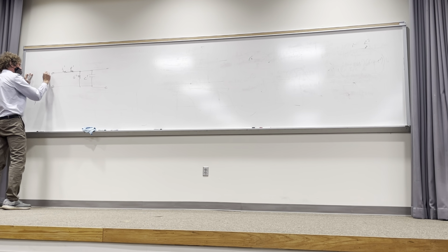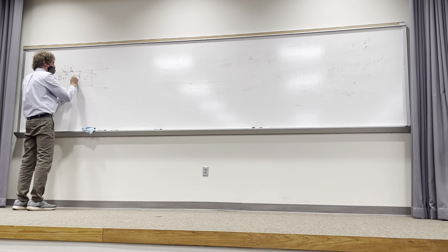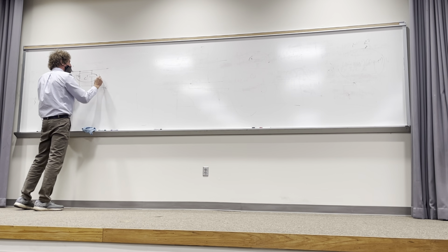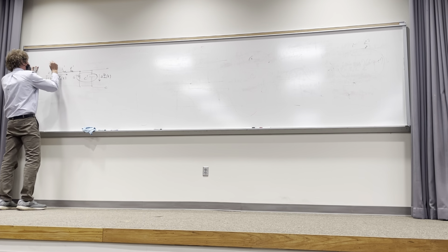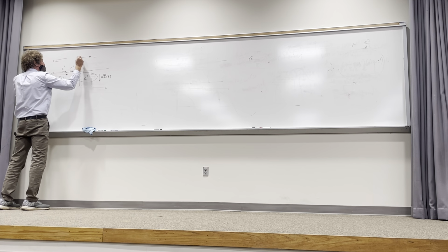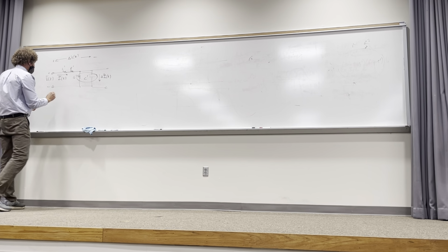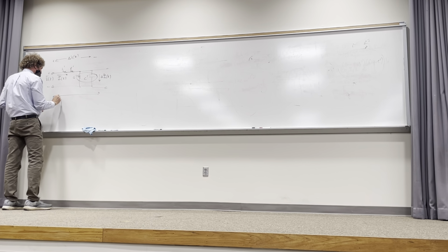And then we take a look at a voltage here. It's going to be some V of Z. This will be a phasor. It has a current I of Z that is also a phasor. And there is some loss current here, and that's delta I of Z. And there's some differential voltage that will be lost between here and here, and that's going to be a delta V of Z. You can forget the Z. And this is over a distance, delta Z.